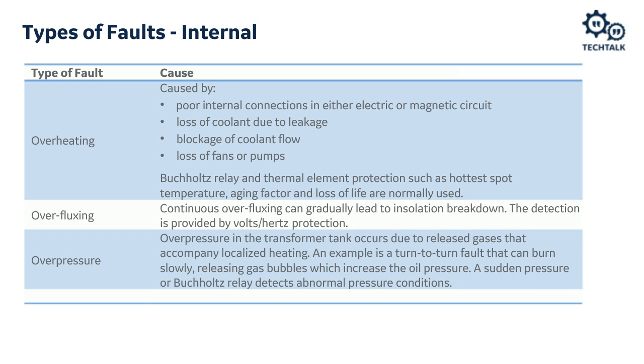Gases are produced by the breakdown of insulating oil, which can be caused by overheating, which would be a slow gas buildup, or by arcing, which would be a rapid gas buildup. In our transformer relays, we could use some of the thermal elements. However, these should be employed more as a backup or supplementary to a Buchholz relay. Since our relay is looking primarily at the electrical signals and not at the physical medium within the transformer, it might not necessarily be quite as accurate or as fast at detection.